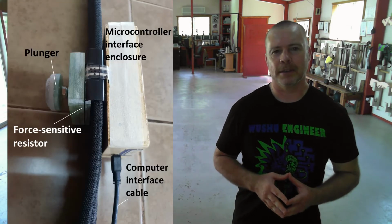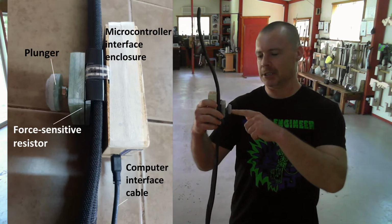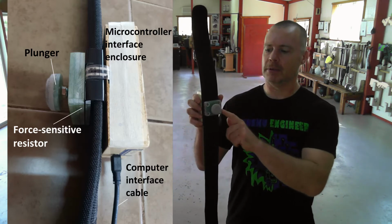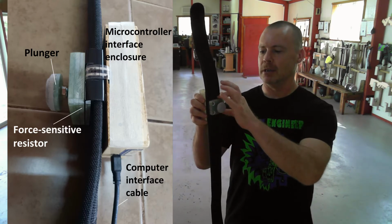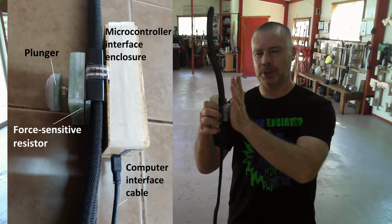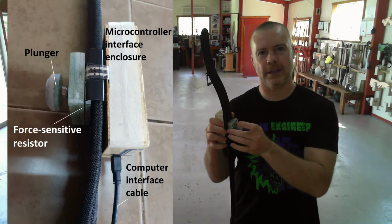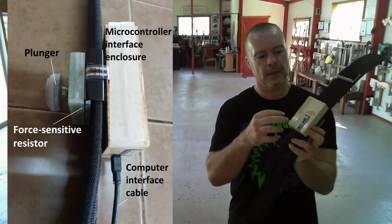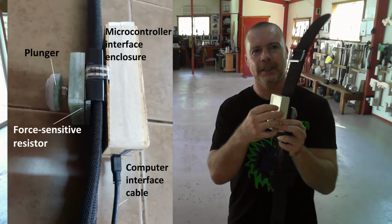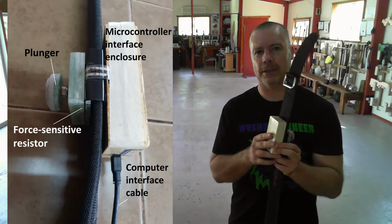The belt sensor incorporates a plunger which presses, actually I can show you here, a plunger which presses against a linear force sensitive resistor, which is located within this G10 fiberglass box of construction. When the front pad of the plunger is depressed by a force pushing against it, the linear force sensitive resistor reacts to that, sending a signal to a microcontroller processing unit, or interface unit, which is located in this box behind. And this in turn sends data to a computer user interface.